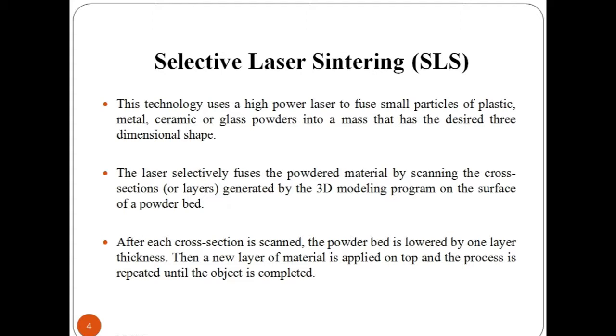Let us discuss selective laser sintering technology, which is an additive manufacturing technique that uses a laser as a power source to sinter powder material. It aims the laser automatically at points in space defined by the 3D model, binding the material together to create a solid structure. Some SLS machines use single component powder, such as direct metal laser sintering. Powders are commonly produced by ball milling. However, most SLS machines use two component powders, typically either coated powder or a powder mixture.